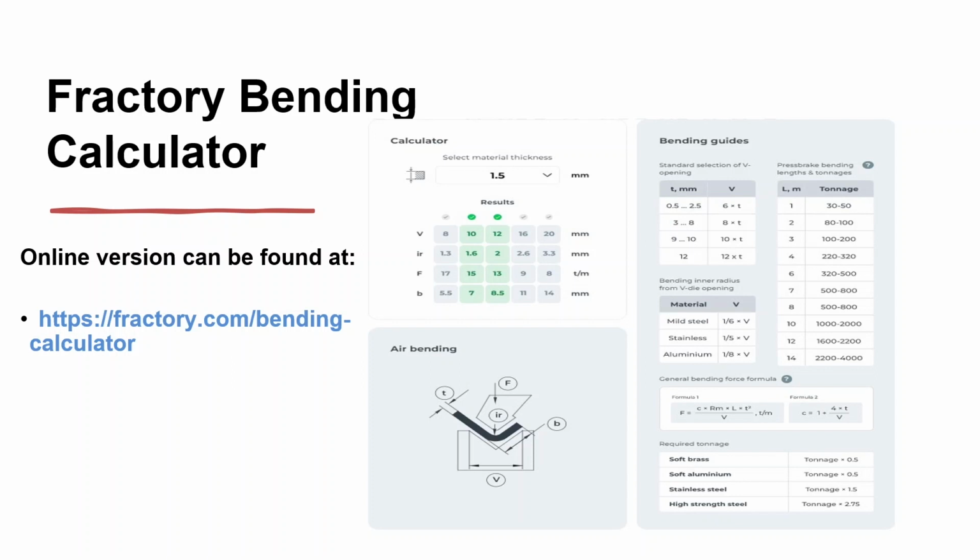The press brake has this blade which comes down. This has a radius at the end. That's the bit which touches down onto your workpiece, which would be resting horizontally across what we call the V-die at the bottom. The blade pushing the material into the V-die is what causes the actual bending, gives you your angle, and also gives you your radius internally inside that bend. So for a given thickness, these typically will be the toolings that we'll be recommending. Our calculator will show you the V-die that we've typically used, the internal radius of that bend, which you'll include in your design, and the force that will come down onto the actual material when using that radius. That can then be iterated back up to the material to make sure your material doesn't crack.